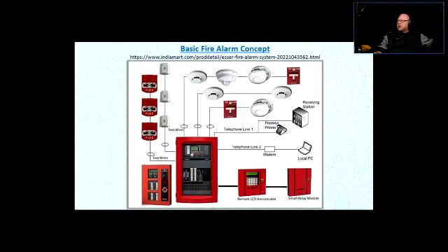And on the display, there will be an indication of, let's say, smoke detected in some air ducts, or heat detected in the furnace room, or pull station pulled in the east wing, door number 7, or something like that, right? So this would be something that looks like that. There will be a satellite panel, and another satellite panel could look like this. This is just an annunciator that would help you with identifying the condition, right?